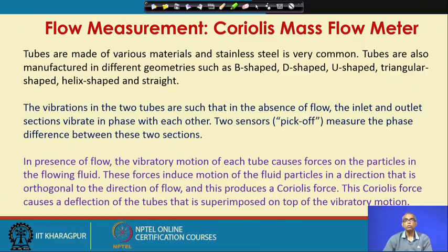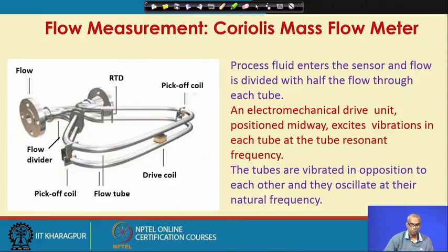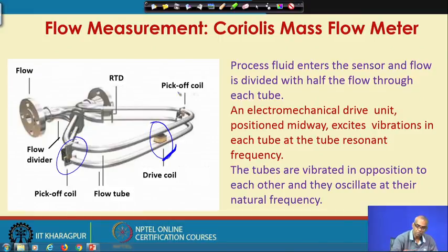This vibratory motion was caused by the drive coil. So, the drive coil causes the vibratory motion, and these two pickoff coils measure the phase shift between these two vibrations in these two sections.